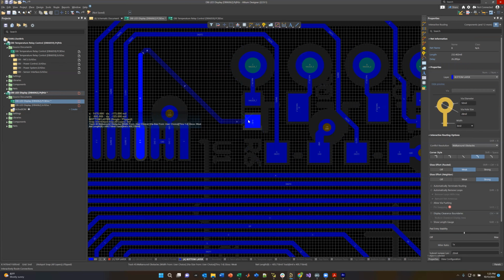And when you route things, you kind of group all the parts together. So for instance, we were looking earlier at the relay. The relay had 2 MOVs, the relay itself, this capacitor, diode, and transistor, etc. Well, when I did it, I actually found all those parts and kind of grouped them together. And you can rotate the part around using the space bar here. You can rotate around and get everything lined up where you have really short traces between everything.